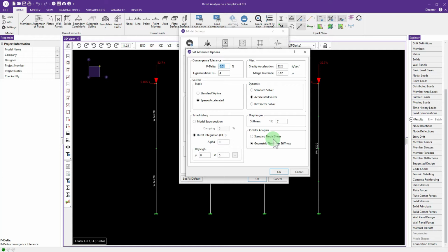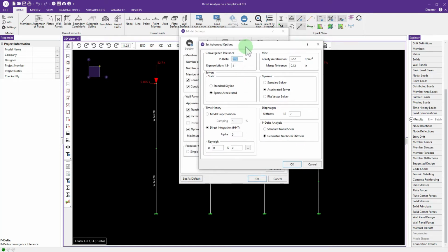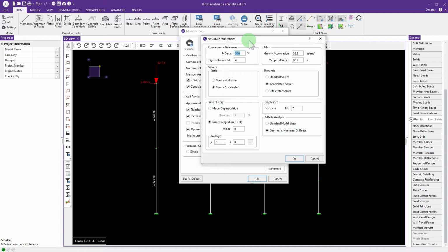Using the geometric stiffness matrix analysis allows you to basically include the stiffness reduction due to compressive load directly in your stiffness matrix analysis. So this is a more generic and direct way of doing this. By the way, this is the way SAP2000 does it.